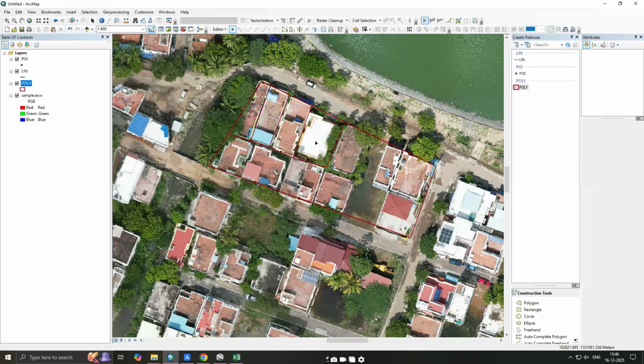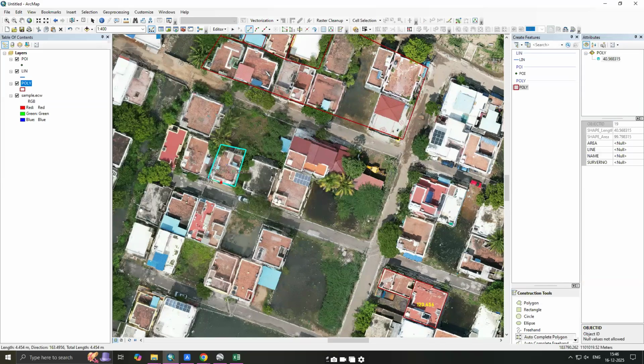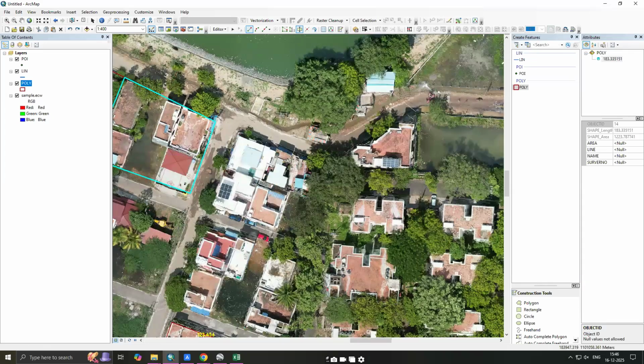So that the work timing will be very much reduced, because in this case, I'll draw one polygon, go to autocomplete, start here and finish. Again go here, finish. Whereas if it is cut polygon, I'll draw one polygon, select it, and it is also possible to make multiple cuttings at the same time. See, I'm doing so. All this cutting is done in a single stroke itself.